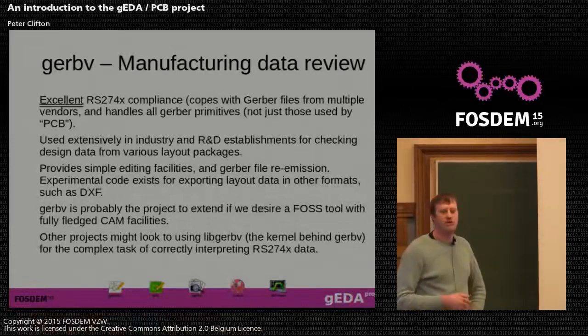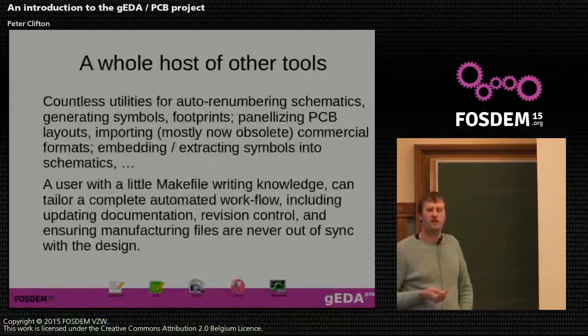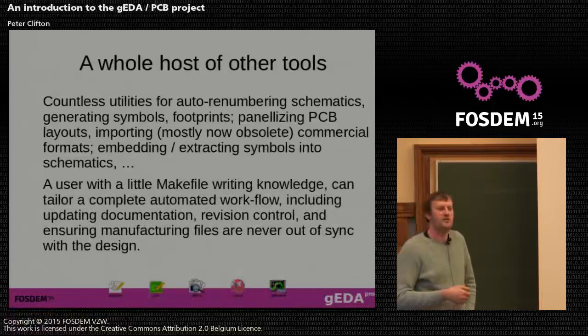And we have a whole host of other tools. If you install gEDA, in your bin folder, if you have a separate one as I do, you'll find quite a handful of little binary tools for reading obsolete formats that no one's used for 10 years, mostly. For renumbering schematics, again, separate tools exist for refactoring your schematics and saying, I want to duplicate this page, and I want everything I've got on my master page to be plus 100 on the refdes, plus 200 on the refdes, and we can make duplicate schematics that way.